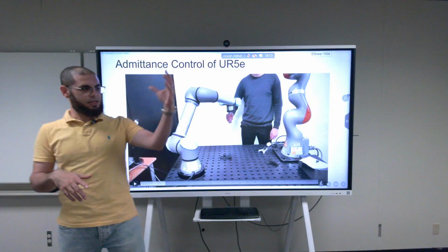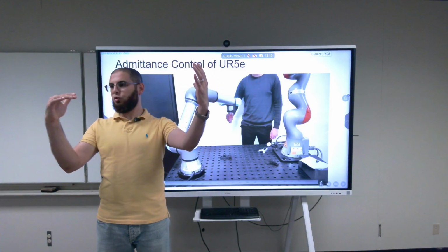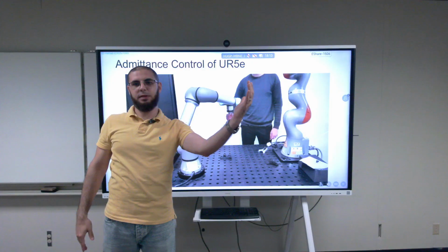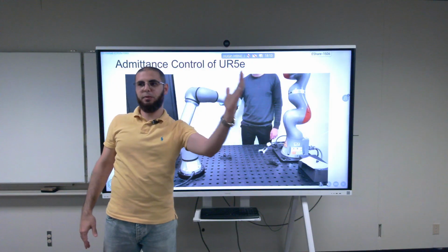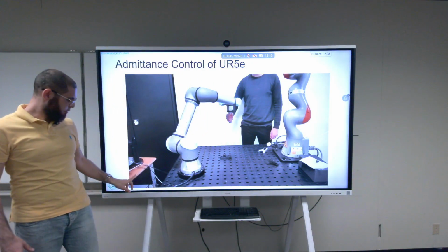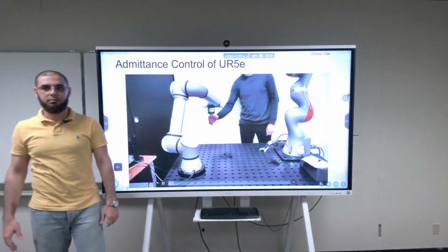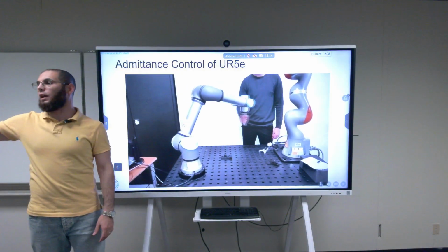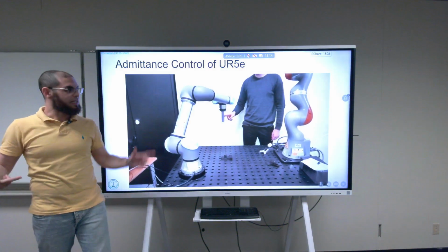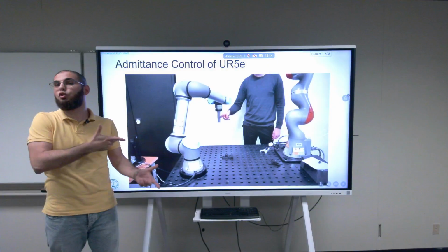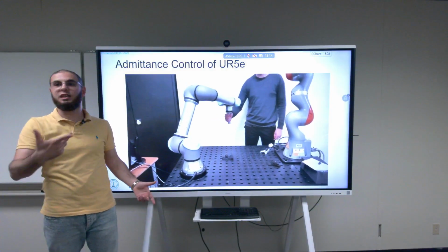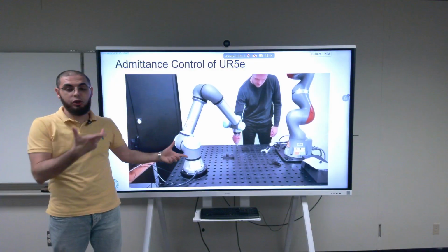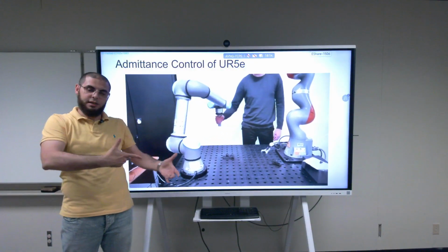If this is the robot arm and I have an impedance controller, and I push it, it pushes back, right? When I remove my hand, what happens? It comes back. There is a spring that brings it back, right? What is happening here? It stays at the last position. Exactly. It's like the desired frame itself is just moving around. You're calculating Q double dot, which means Q desired is changing. The desired frame is changing, and the robot is following the behavior that you want in an impedance.